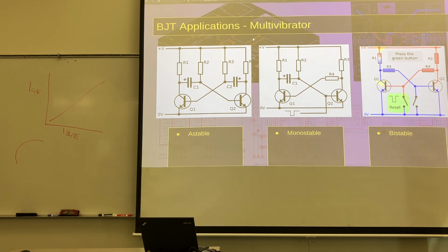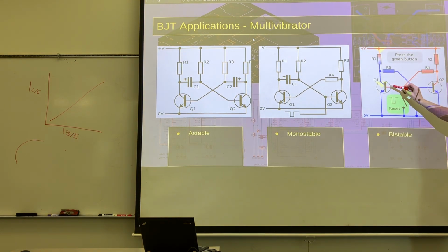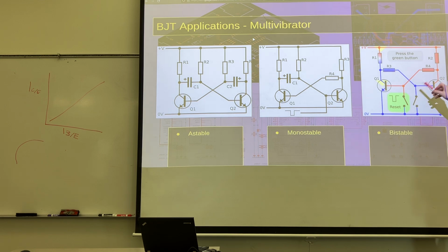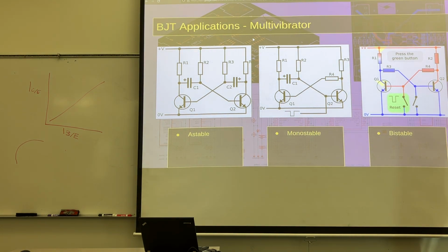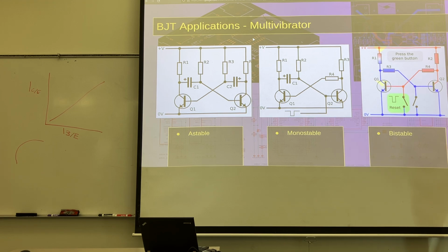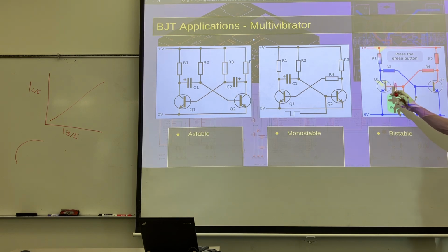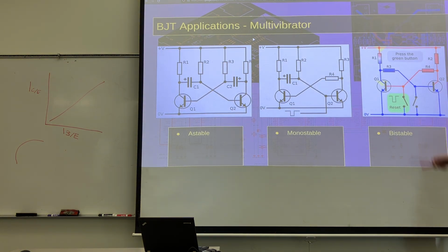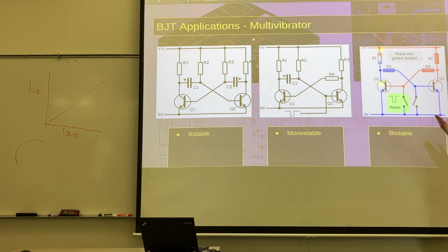Okay. So this new voltage drop across R2, what's after it? It's flipped. Yes. After it's flipped and this is conducting, then all the voltage drops across this. This is now 0 volts in this direction, so this remains shut even after this reopens. So this is a transient kind of button. You're pushing something, and it is shorting this just long enough to make sure that this stops conducting and this starts conducting. And this itself does not do useful work, but it does create a system where you can say, I press a button and it swaps between 2 things.